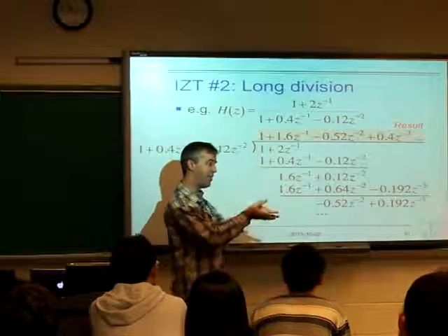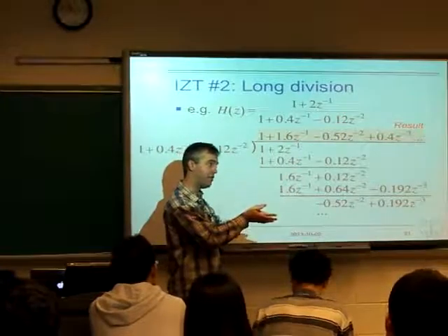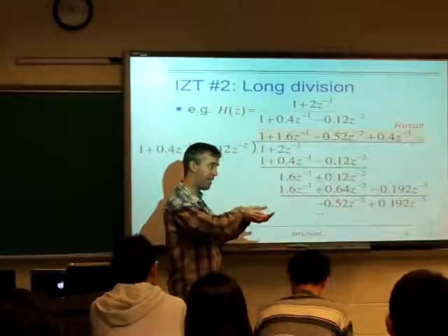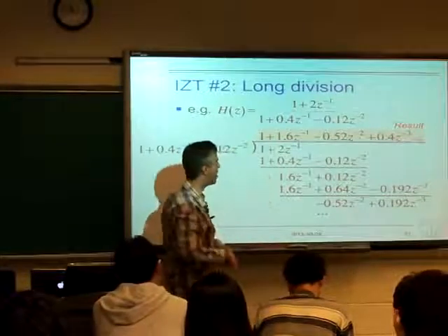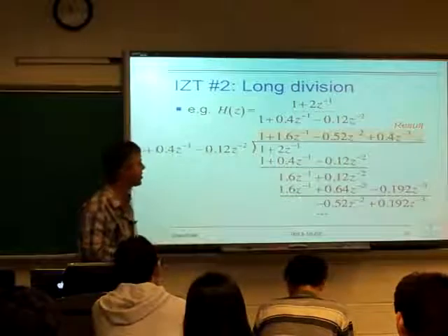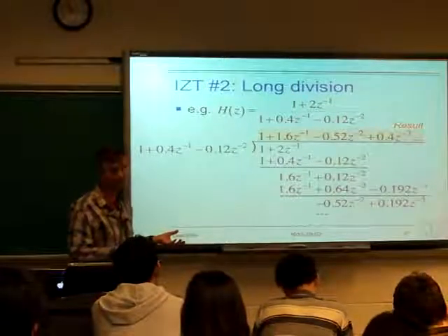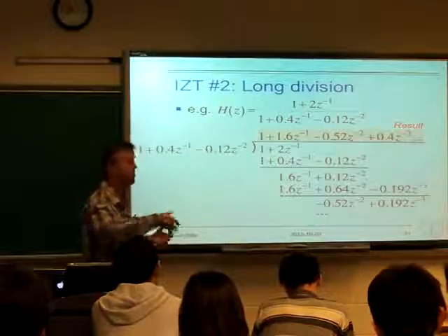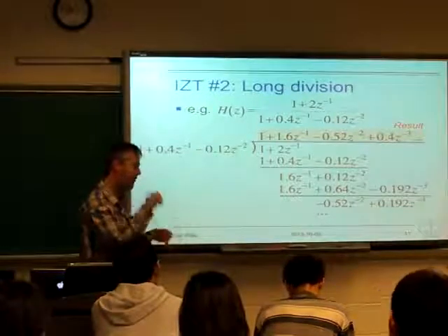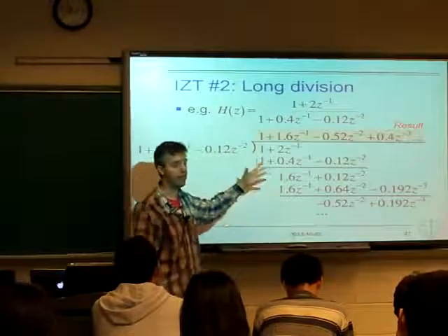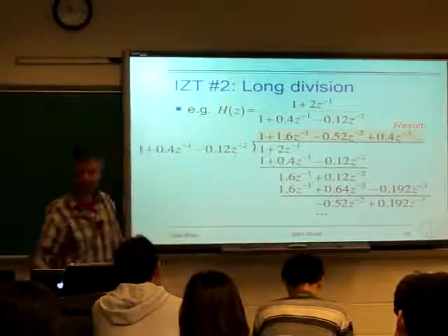And if it's an intersection, it means that it's the sum of two closed form expressions, one of which has a certain region of convergence, the other which has a different one. So you should be able to identify those and figure it out. But in general, you'd have to do extra work to make it work. But we almost always want to talk about causal systems, systems in which nothing happens until you put a signal in, then something happens, which means they're going to be right-sided like this, and so this is the case we care about.